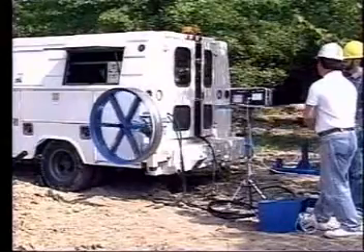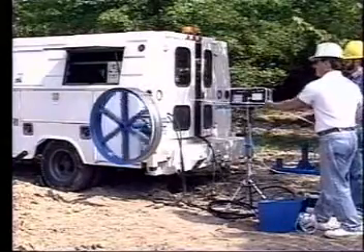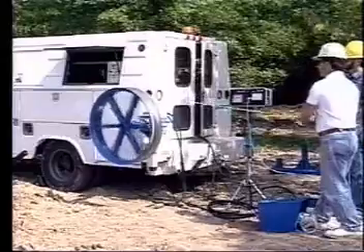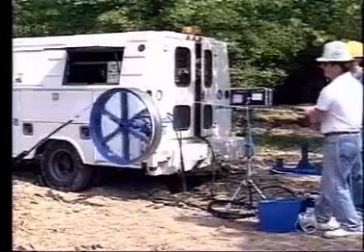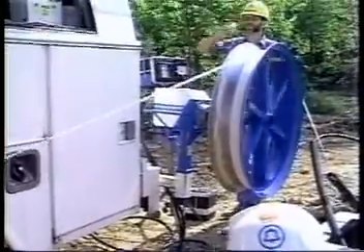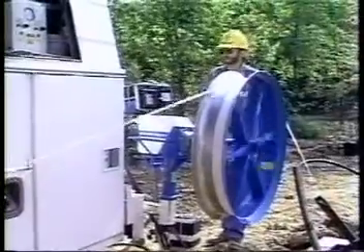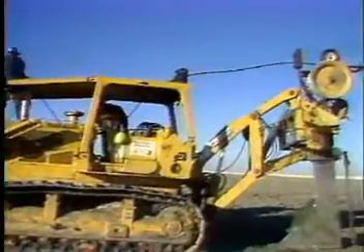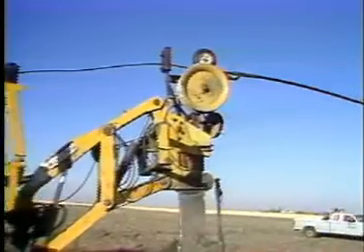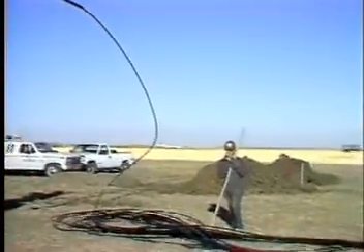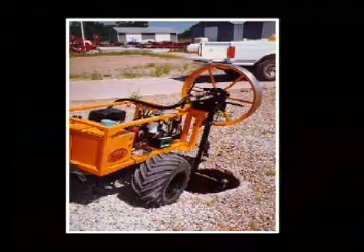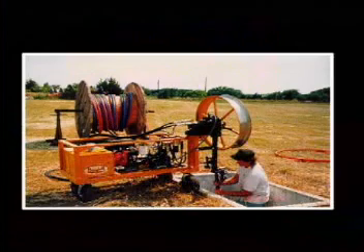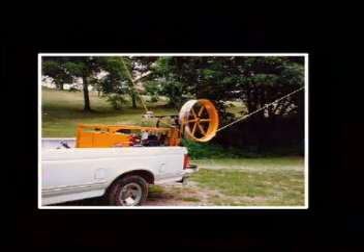An alternative to center pulling is mid-span assist, where powered winches deliver pulling force to the cable at periodic points along the span, rather than at one point. This eliminates the need for figure-8ing the cable on the ground, thus saving time, labor, and the possibility of cable damage. The winches have built-in tension monitoring, allowing them to balance pulling force along the cable route.